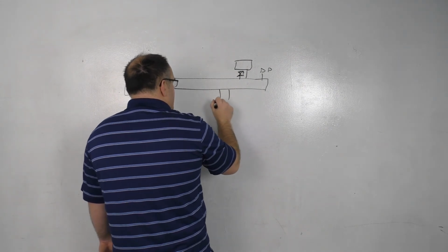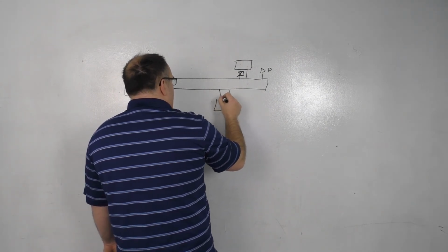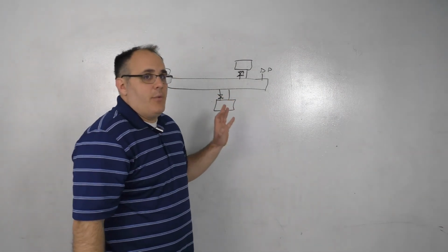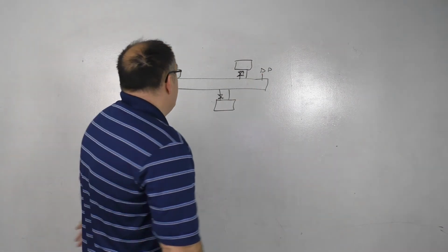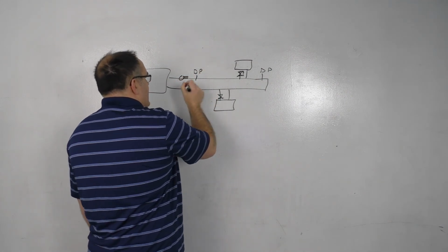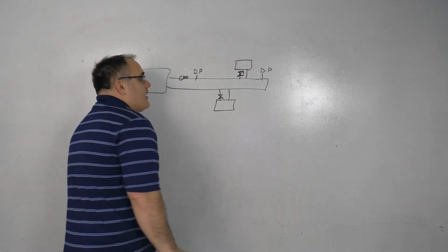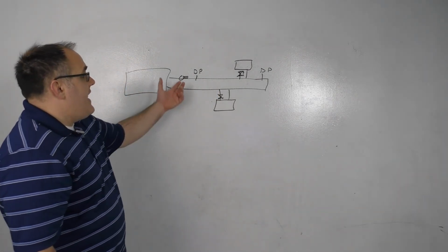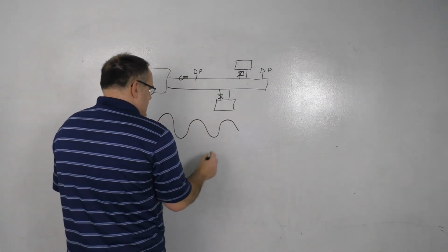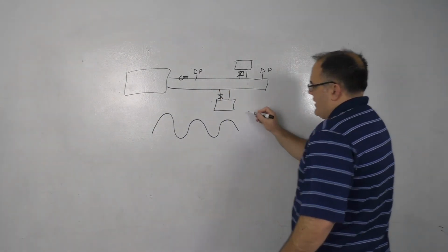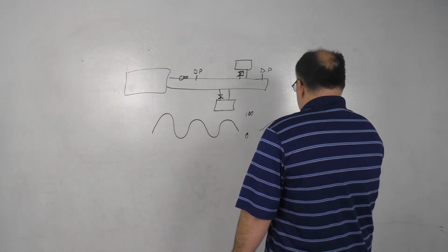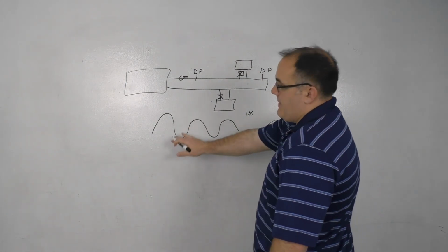I'm not actually taking the time to reflect how the coils and valves would be placed, because that's not what we're focused on here. We're focused on DP. I see a lot of folks putting the differential pressure sensor here, and you've got a pump and it's hitting the differential pressure sensor right here, and it's overpowering that sensor, and so you get this pump control that looks like this instead of more like this. So that would be 100 and 0. So instead, you should have something that looks kind of smooth, not these peaks and valleys.